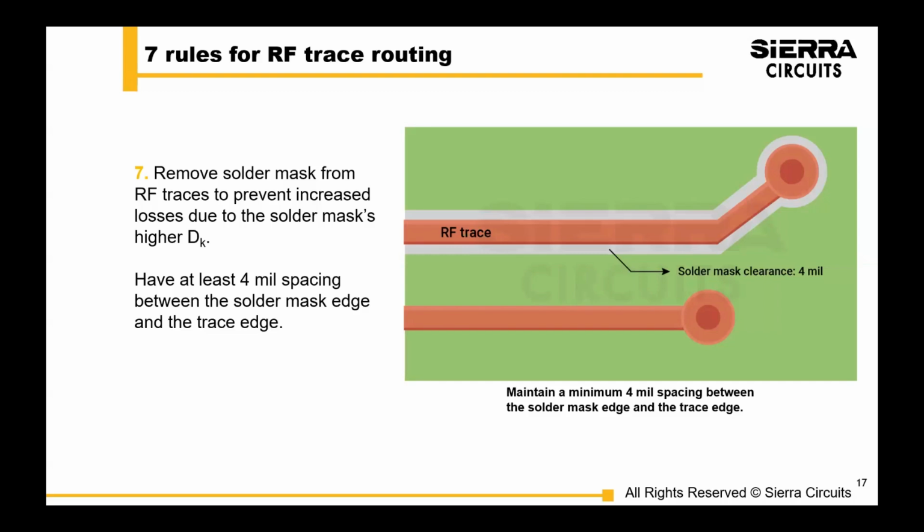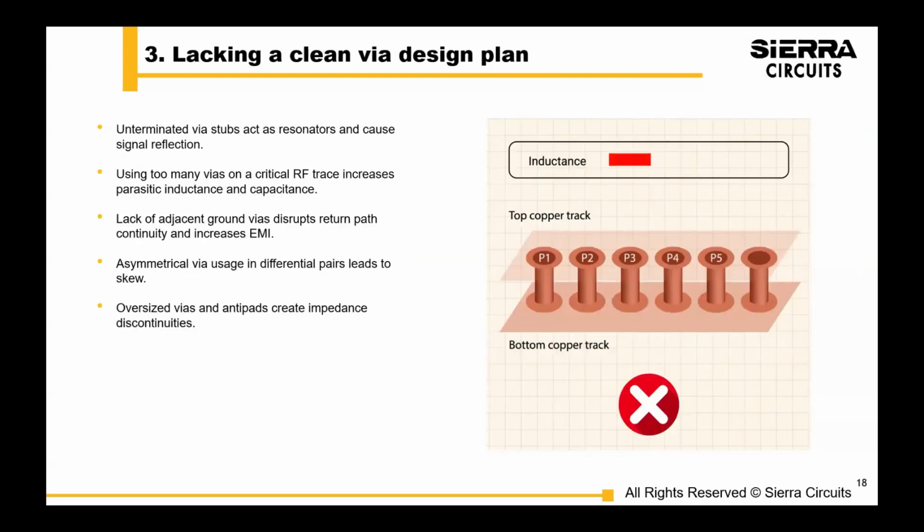And if you do that, have a good gap between so that the registration is not an issue for your manufacturer, the registration of the solder mask to the imaged and etched trace.